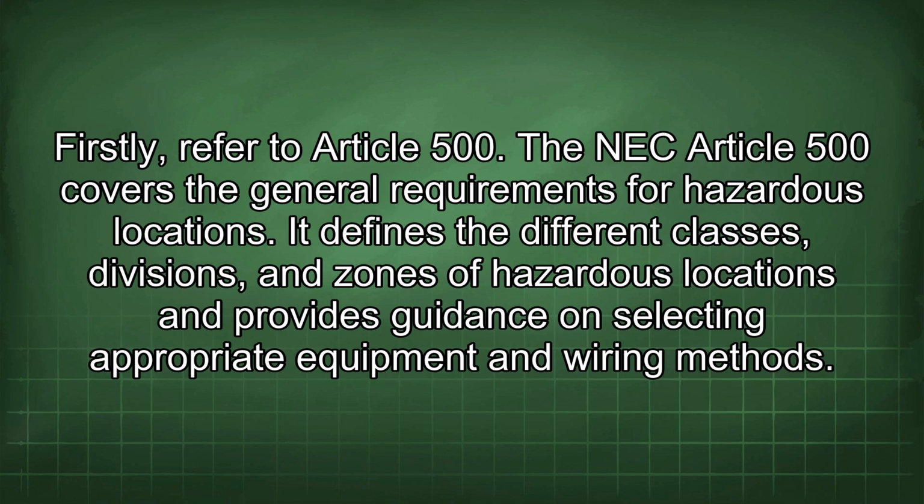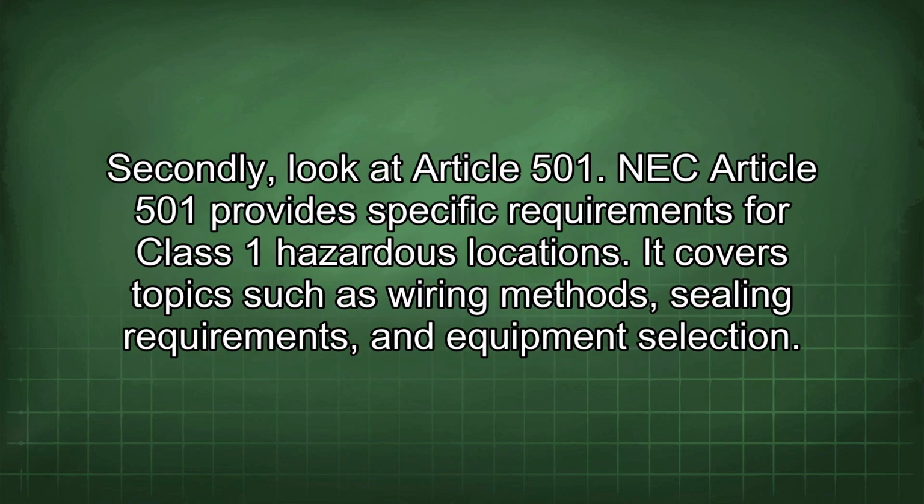Firstly, refer to Article 500. The NEC Article 500 covers the general requirements for hazardous locations. It defines the different classes, divisions, and zones of hazardous locations and provides guidance on selecting appropriate equipment and wiring methods.